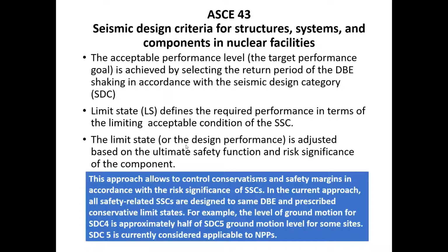And that's very important. To give you an example, if I have a structural wall and I can let it deform to a great extent and it still does my safety function, for example, supporting a safety related component, then I can let it be designed not to a very strict elastic limit, but I can relax my design requirement. That is the notion we are working on.